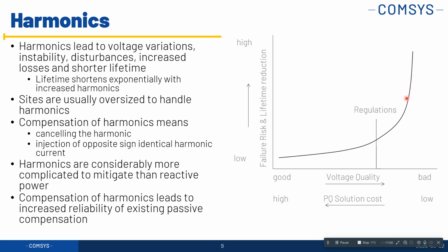Unfortunately, this curve here is an exponential curve. So if you have 1% or 2%, that's more or less no difference. But if you have 10% or 11%, that makes already a very big difference. Yeah, that's a question I often get when I'm out. And it's really on the vertical line here to the right. It can happen very, very fast and cause a lot of damage to measuring instruments and expensive robots or your production. So when you're over 8%, we can say for sure you're going to have problems. Between 5 and 8, if you don't have a problem, you don't have a problem, but there could be problems already there. Under 5%, not many really have any bigger problems.